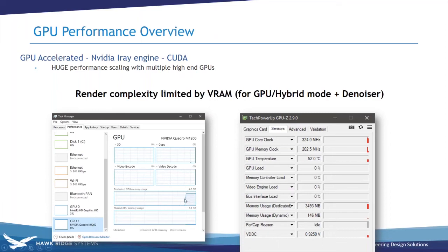If you have an older system, Windows 7, there's a free third-party utility you can download called GPU-Z, unaffiliated, but it's a nice tool for diagnosing graphics card things, and it will show you GPU load and memory usage. You can confirm with any of these tools that Visualize is actually using the graphics card the way it should. So I just want you to pay attention to what can max out the VRAM.